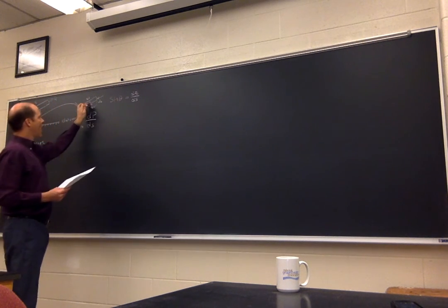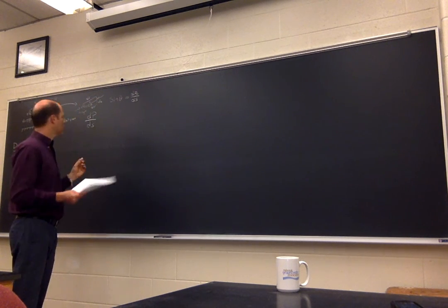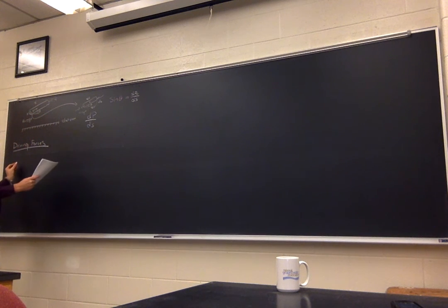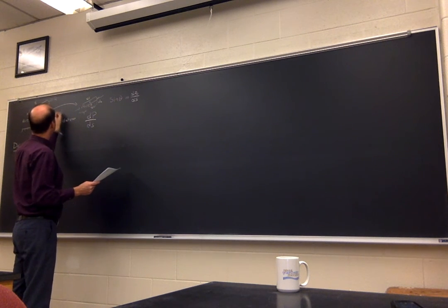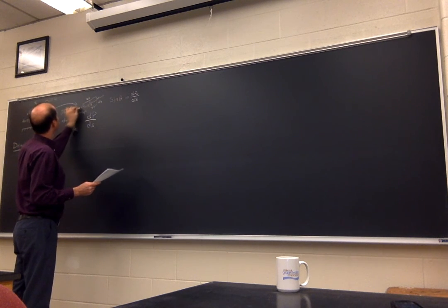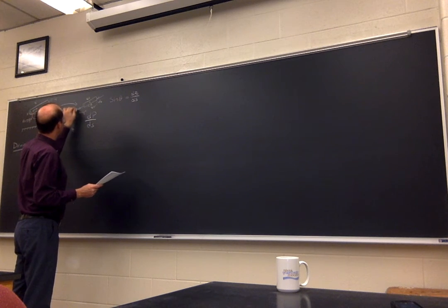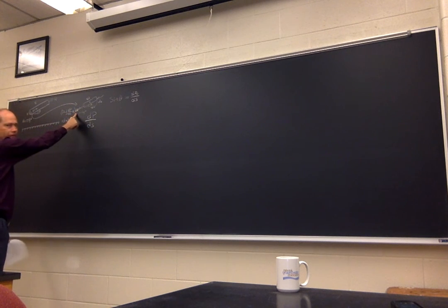And that is 1/2 of the distance away from the centroid in either direction, such that the driving forces going forward are related to the pressure here, which is P minus 1/2 of the total change in pressure over the distance times that distance times dA. That is the force. So pressure times area gives us force.